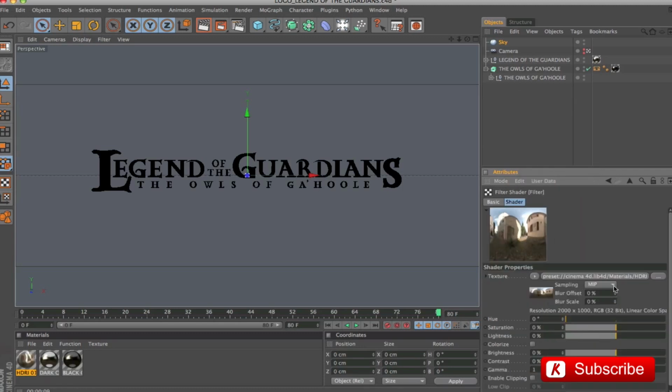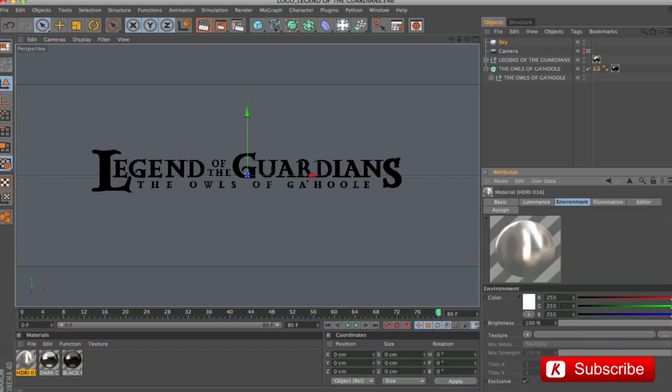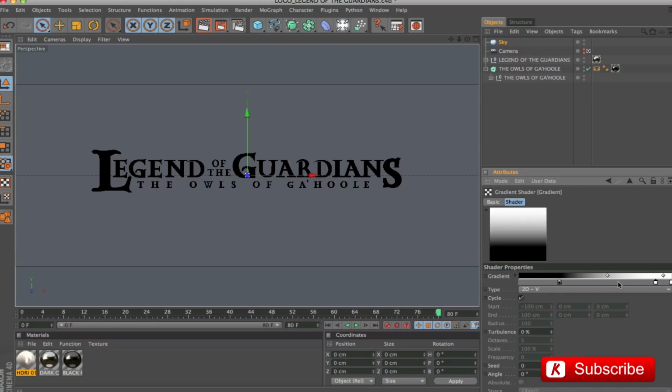Inside it, we put the following values: 17 to blur, saturation to minus 20, brightness to 9, and gamma to 0.9. In Environment panel, modify the color, 234, 196. And we apply a Type V texture gradient. Follow on the video the distribution of the colors in the gradient bar.